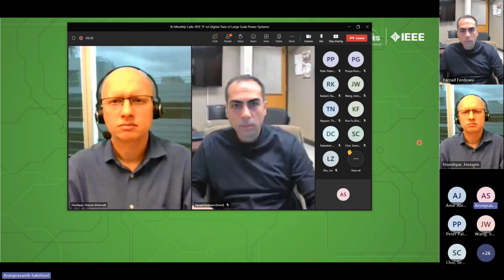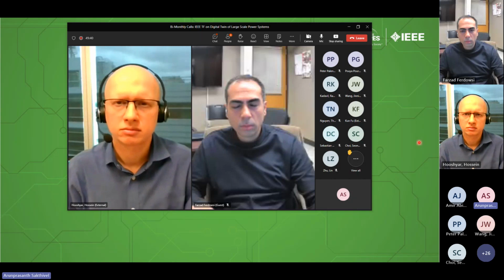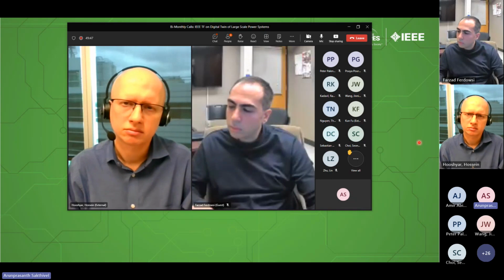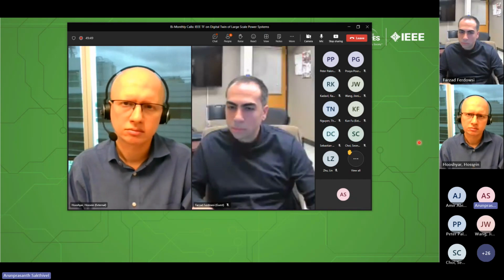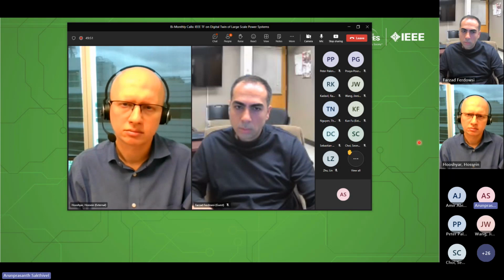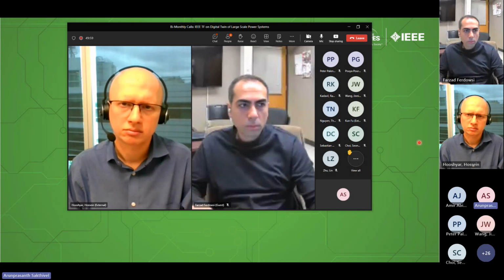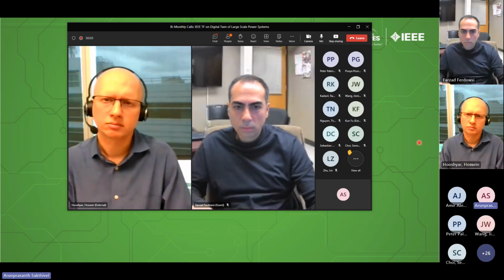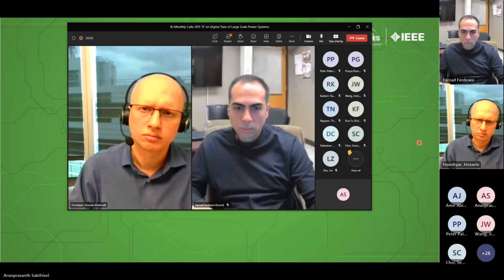The snapshot data from EMS has the load changes, generation changes, and also the network. For example, if a transmission line is out of service when the snapshot is taken, it will show as out of service in the snapshot data, so that in the RTDS simulation, all the branches and shunt connections or sources were modeled using breakers.